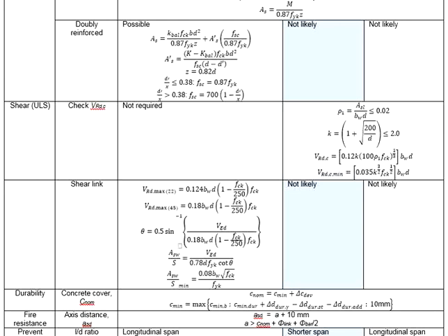But what you see in the industrial practices, although they declare the design is based on the Eurocode, they are still using mild steel for the shear links. R6 and R8 mild steel is easier to work with, especially when they need to bend the mild steel bar manually. That's why the local industry prefers to use mild steel bar as the shear links.